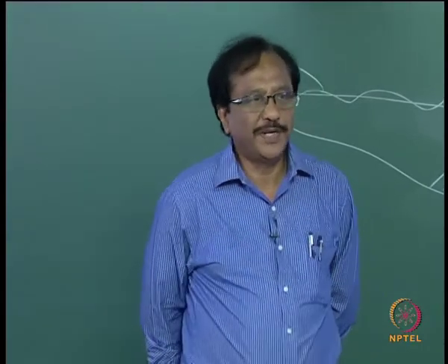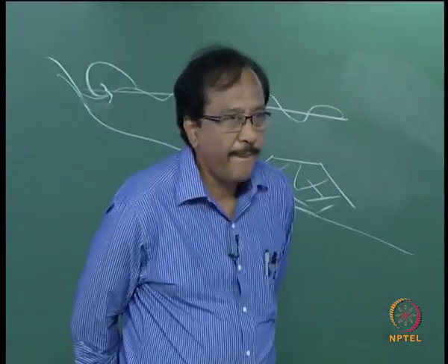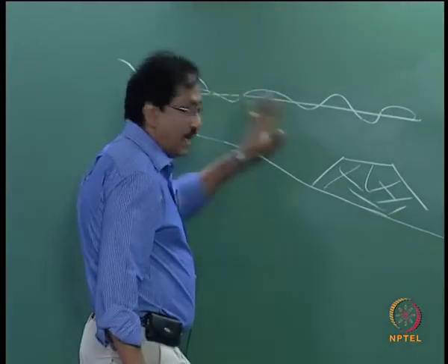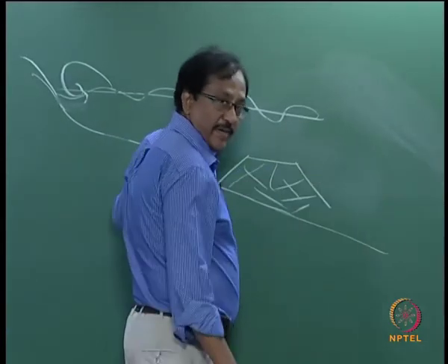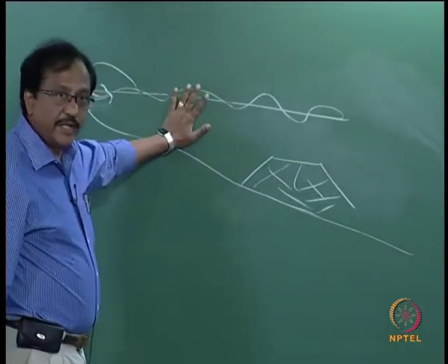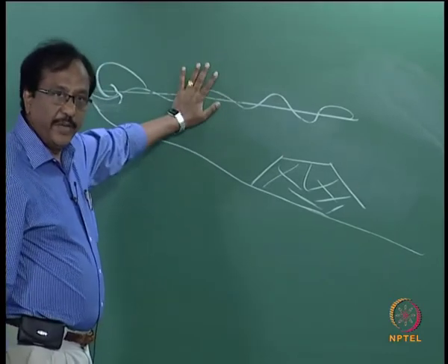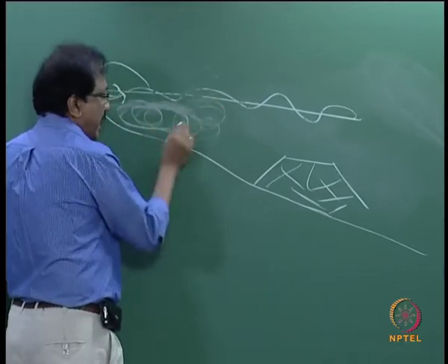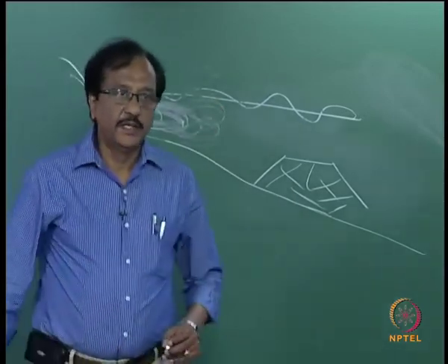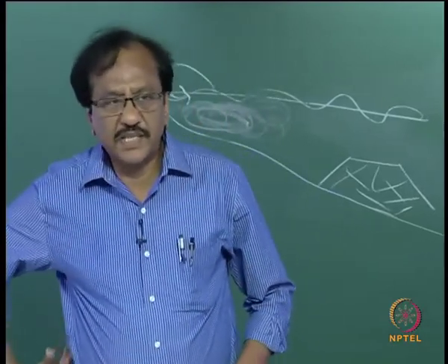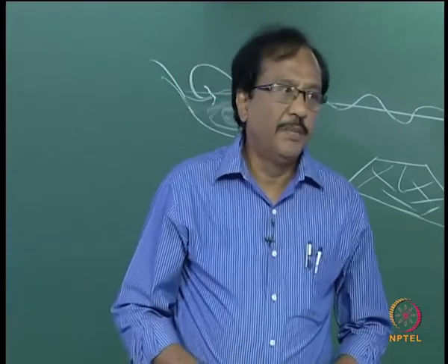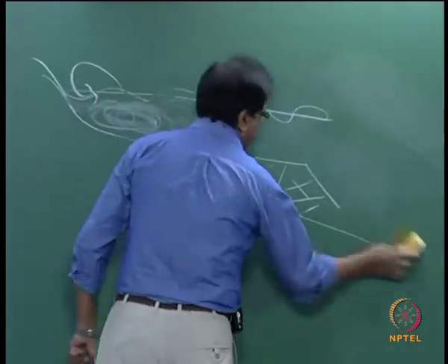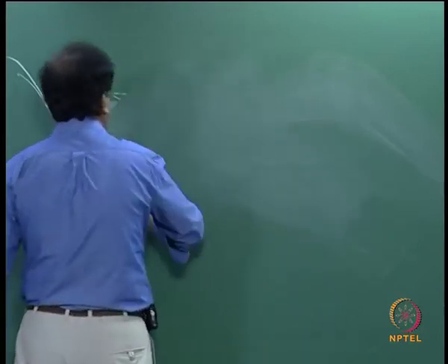If energy dissipates, what happens to sediments? Sediment will deposit where? Will it deposit somewhere here or here? It will be depositing here, because here is the location where the waves are attenuated and the energy is dissipated, so the energy is less here, and you can have the sand being deposited here. So, submerged structures or reefs enhance premature breaking. Okay. So, this is a concept which has been widely adopted in certain locations.